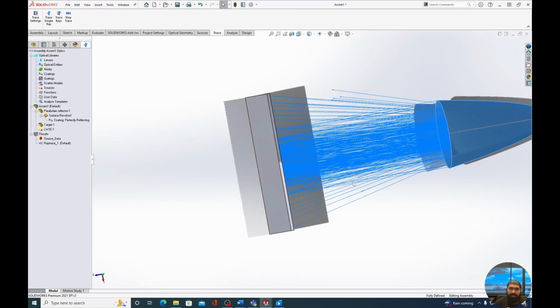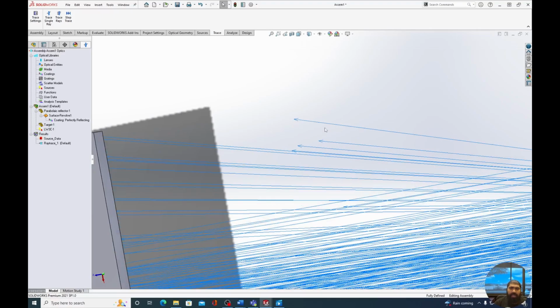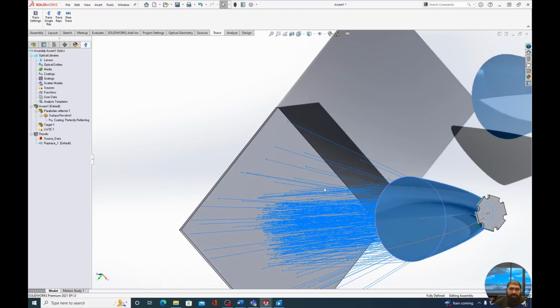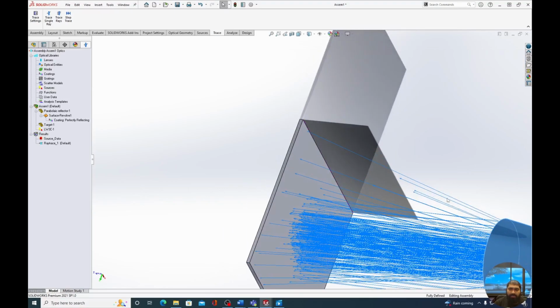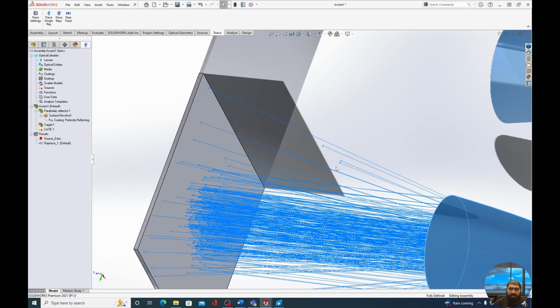And thus we see our traced rays. You'll see how far some of these beams have gotten. These ones that disappear here, it's because APEX knows that they didn't hit the surface, so we just had them stop there. That was the setting that we placed earlier that said only propagate beams that don't hit anything 150 millimeters in space, and that's why they propagate only this far. You'll notice these two go this distance, but this goes a lot longer. This is because this hit a little bit further back inside the parabola, and this hit a little bit further out. So that's why you see that discrepancy.